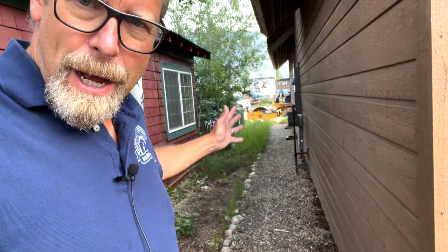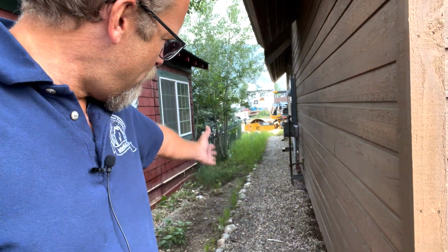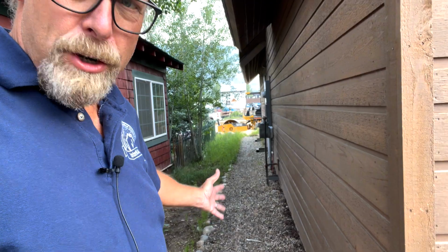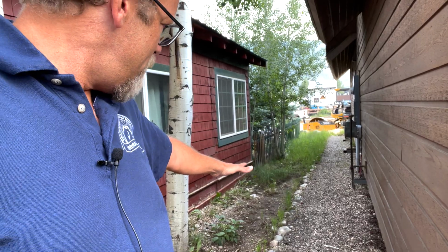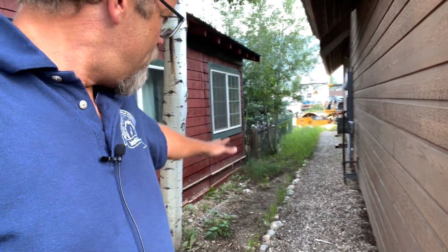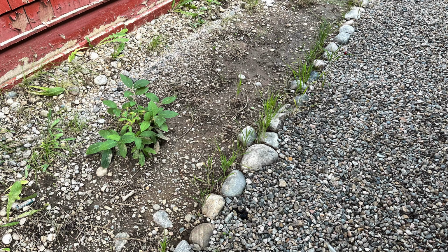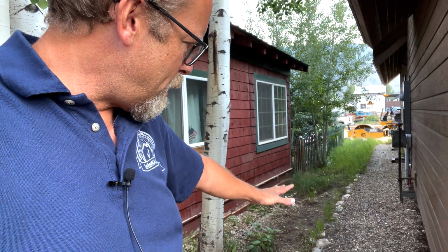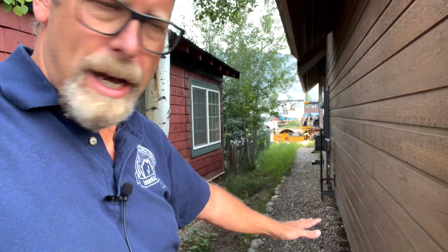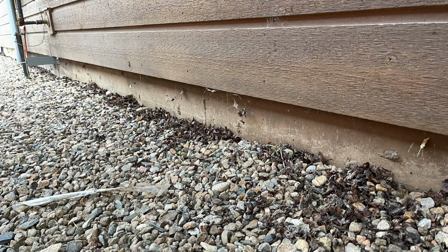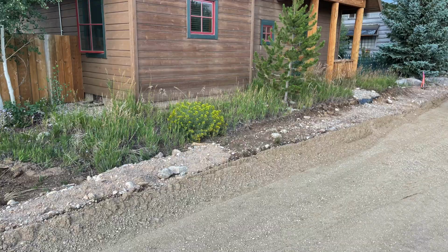And also on the side of the house, you can see no gutters. Rain falls, you can imagine what happens. Hundreds of gallons of water per rainfall falls right here, and what happens? Not sure. There isn't a swale, and actually it's fairly level. The neighbor's yard has grass there, and there's some missing grass, and you can see it puddles up. I don't want water coming towards the house. And on the street side, on the back side, we know that it's graded away.